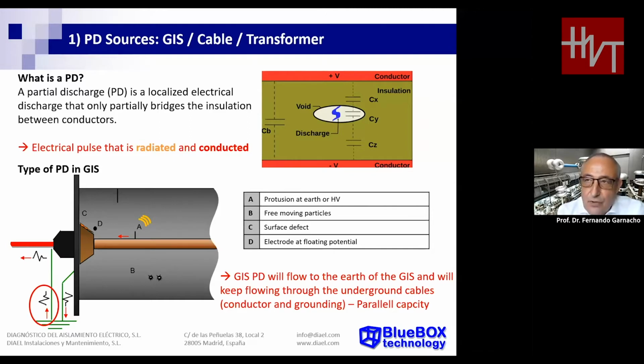As you know, the charge is the integral of the current pulse. So, in conclusion, the integral of a current pulse of milliamps, whose duration is several nanoseconds, gives a charge of around picocoulombs. Milliamps multiplied by nanoseconds involves picocoulombs. It's a small pulse with a small charge that can be measured. How to do it?